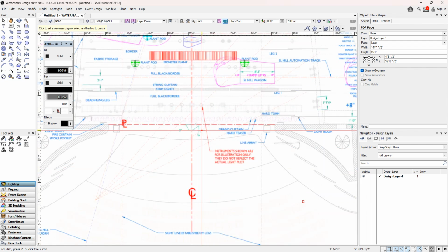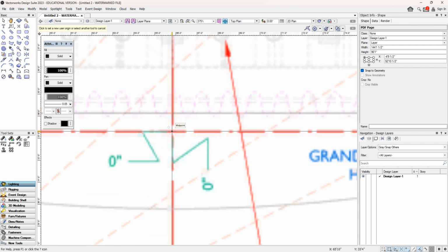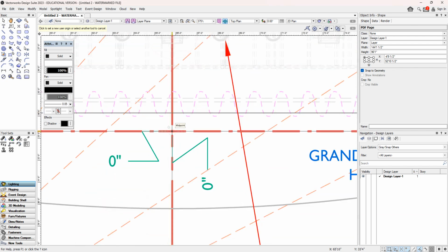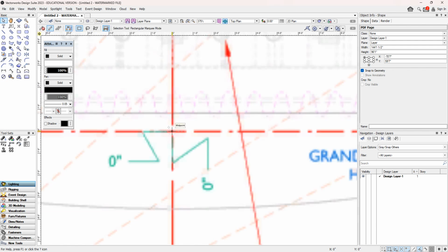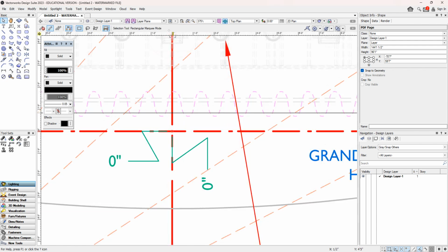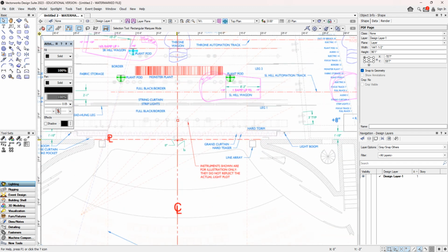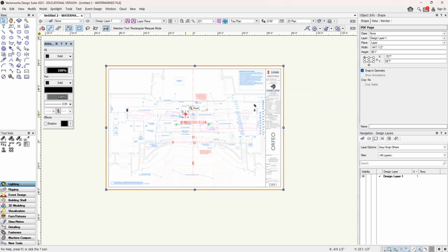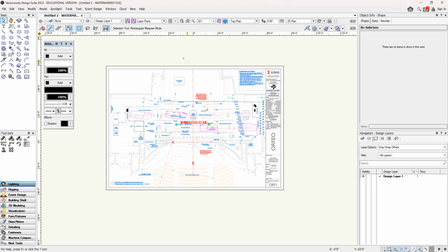And now you see the two crosshairs here. I'm going to go into that center line, plaster line intersection, and I'm going to click. And what you'll see now is that the rulers have renumbered themselves, so that 0 is now at the center line and 0 is now at the plaster line. So we've successfully set 0 to where we want it to be, which is good.